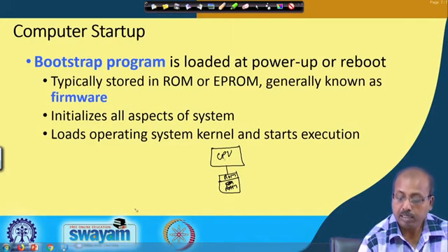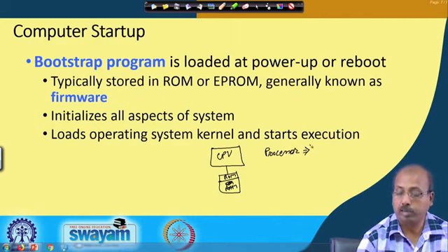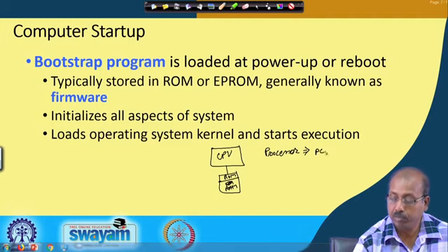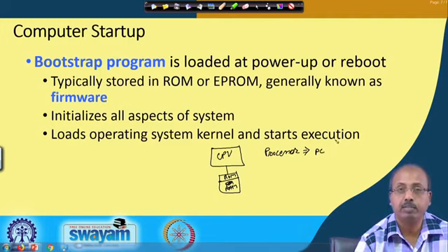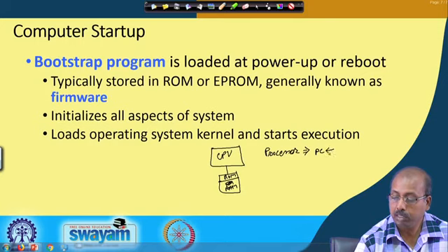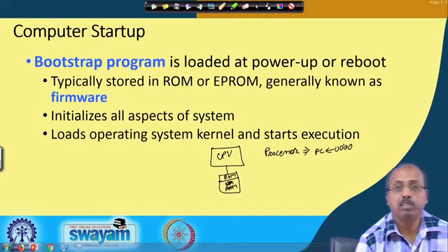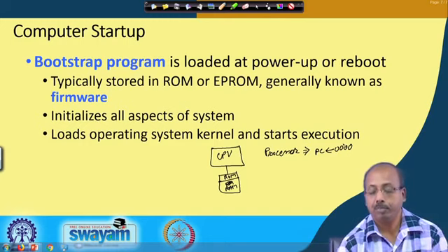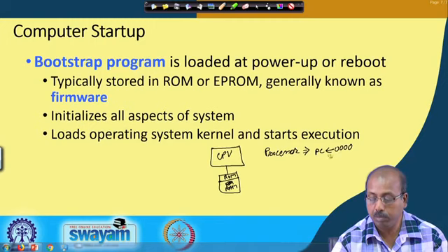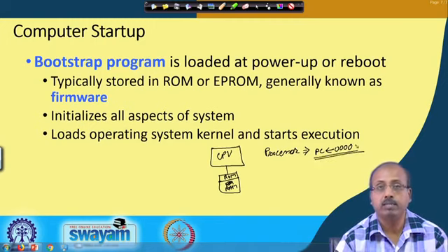So, what does this CPU do? If you look into any microprocessor, you will find that if you reset or power on this microprocessor, its program counter or PC gets some specific value. For example, if you are looking into 8085, it gets the value all 0. Depending on the processor, the manufacturer will tell what the value of this program counter is when the system resets.